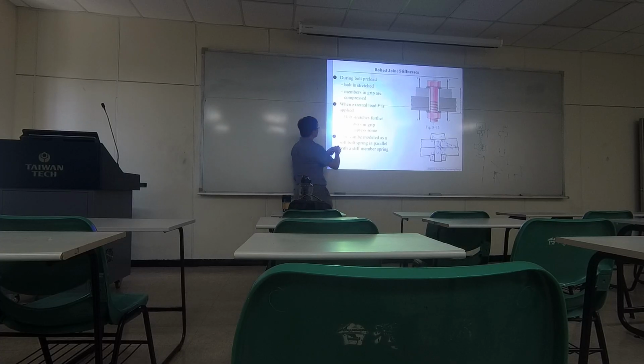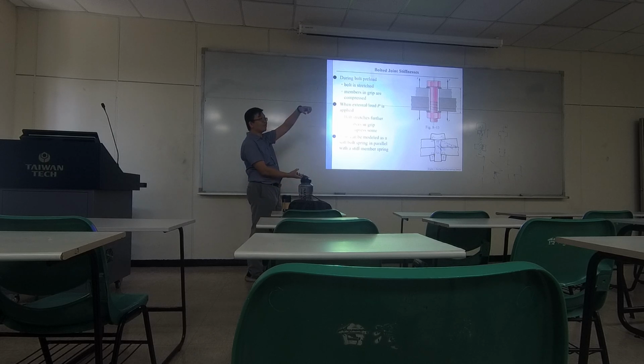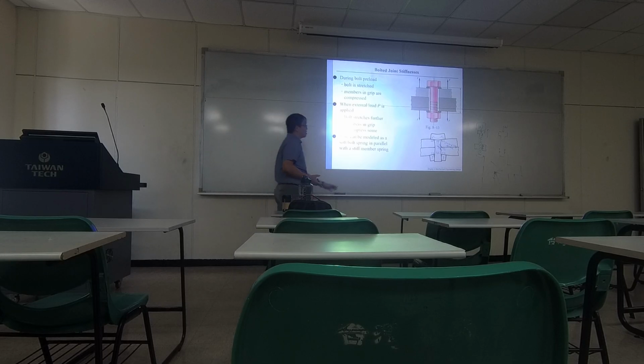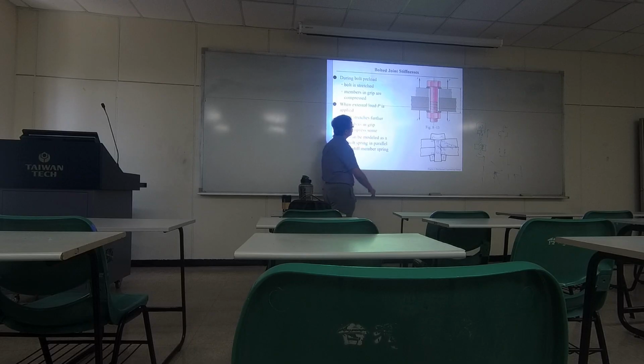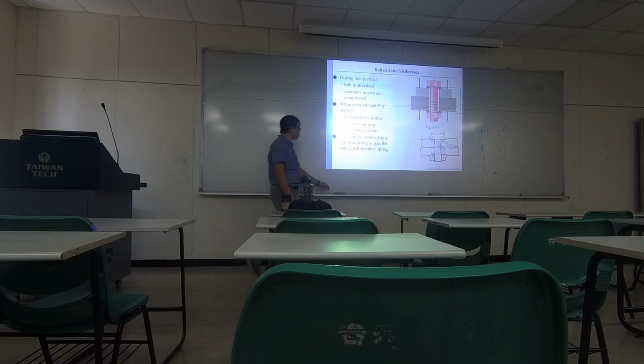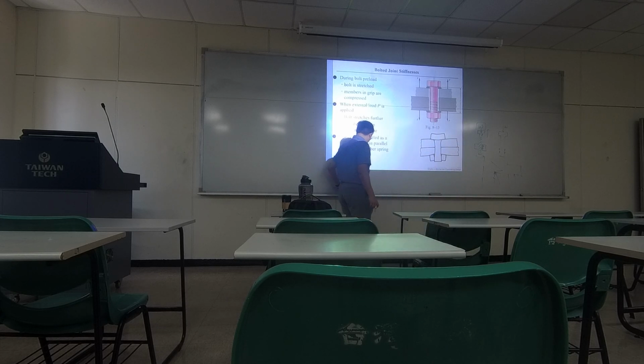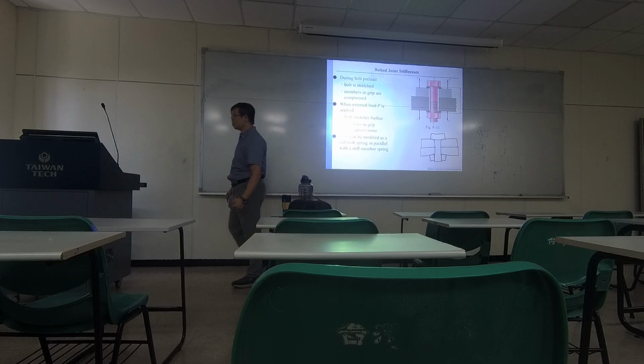So you see, it says the bolt stretches because it's being lengthened. And the material property of the bolt, the thread, the screw, is trying to recover its own shape. So it's like a spring force. It's trying to recover, and that force is going to clamp the plate at the middle. Okay, so you need to understand that when you tighten the screw, you actually stretch the bolt.